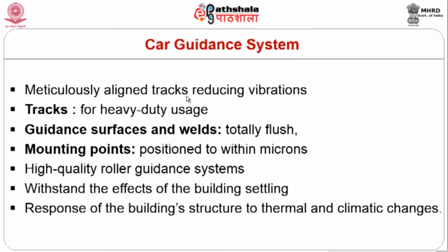And since the cars are going to move up and down for a length of time, durability of tracks is very vital, and therefore we make use of heavy duty tracks for the high rise elevator system. Guidance surfaces and welds have to be totally flush so that they don't hit any components that are around the shaft.